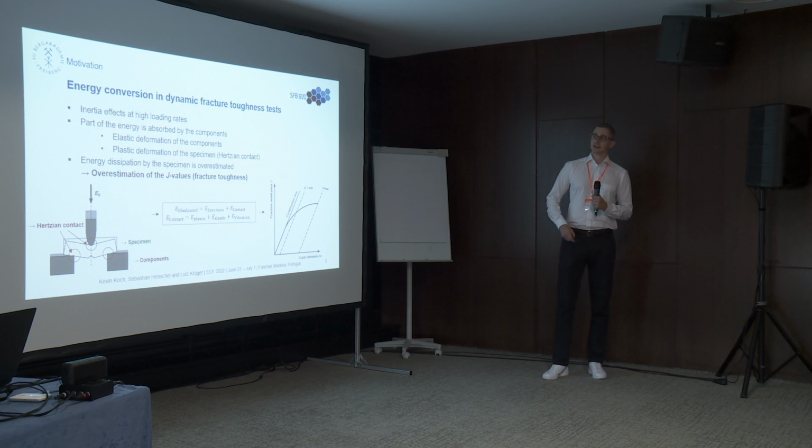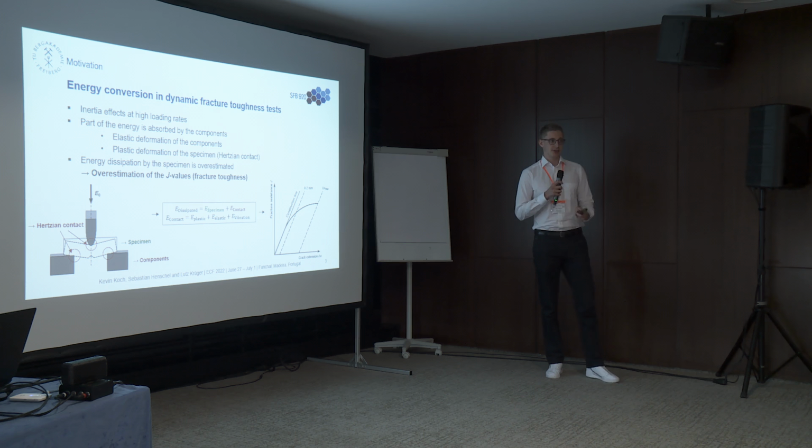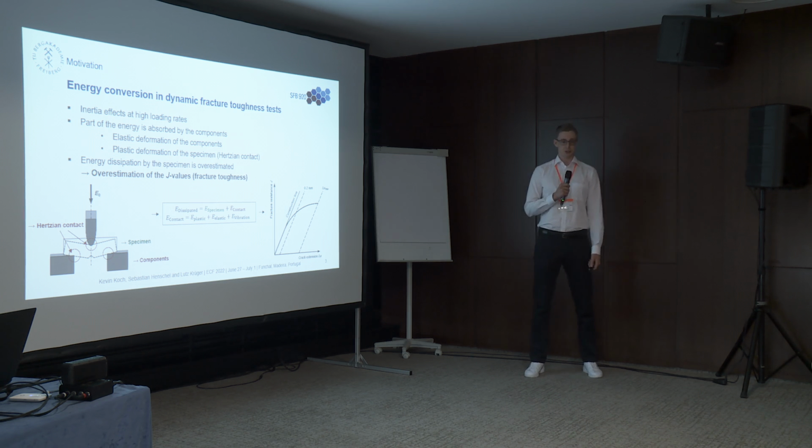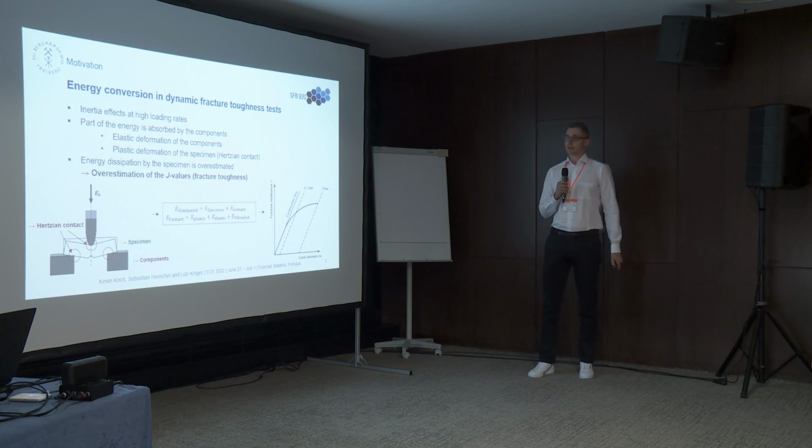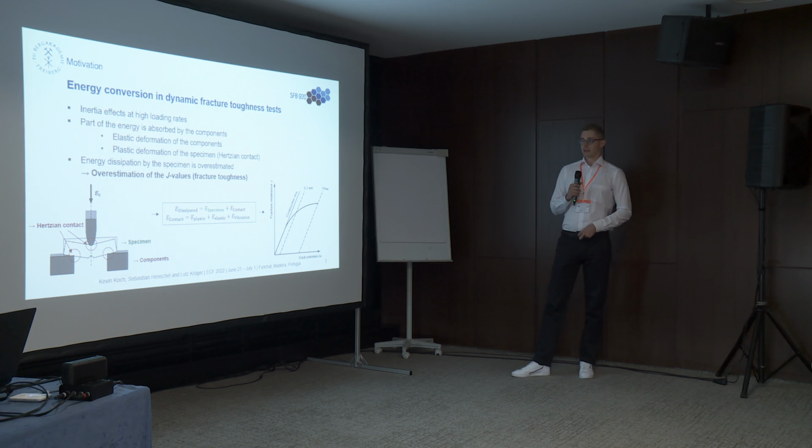So first, compared to static tests, in dynamic tests we have to take into account inertia effects, which can happen due to the increased loading rates, which means that part of the energy is absorbed by the components. If we take, for example, the pendulum impact test, where the impact energy prior to the test is represented by E0, after the impact, the specimen absorbs a part of the energy.